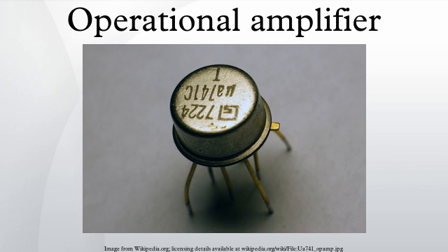Temperature effects. All parameters change with temperature. Temperature drift of the input offset voltage is especially important. Drift. Real op-amp parameters are subject to slow change over time and with changes in temperature, input conditions, etc. Noise. Amplifiers generate random voltage at the outputs even when there is no signal applied. This can be due to thermal noise and flicker noise of the devices. For applications with high gain or high bandwidth, noise becomes a very important consideration.